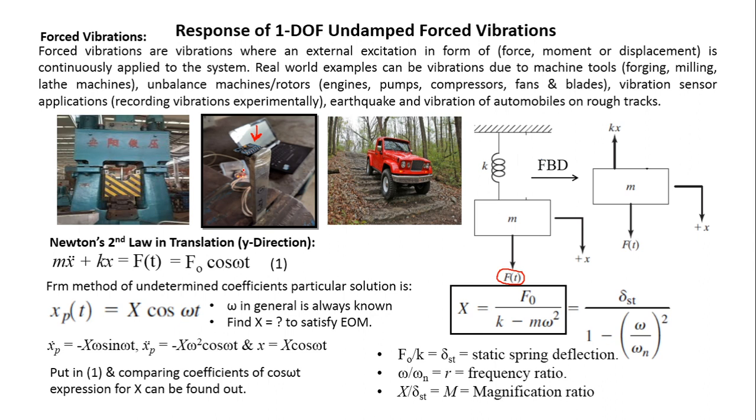So the infrastructure in this sensor is receiving vibration from its base. The base is the cantilever beam on which the sensor is attached. So this becomes a forced vibration problem. So sensor attachments or recording vibrations experimentally is a very good example of forced vibration.